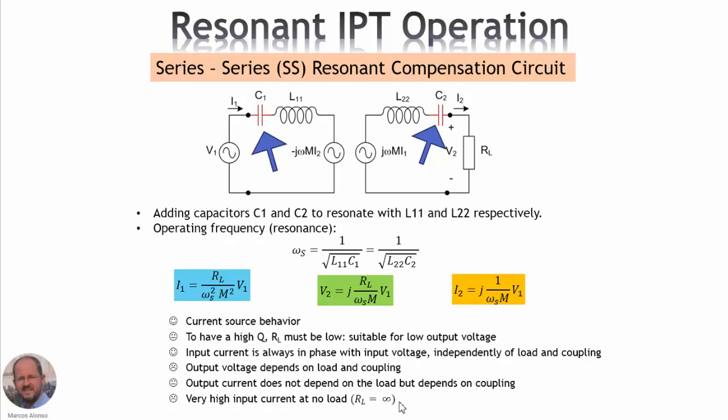And finally, a disadvantage is that if we operate with no load, we are going to have a very high current at the input. So it's necessary to implement some kind of protection against no load operation.